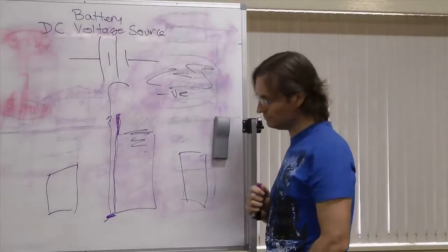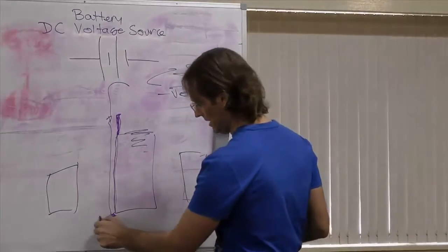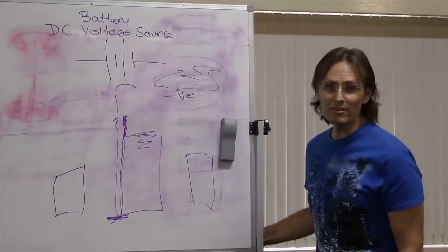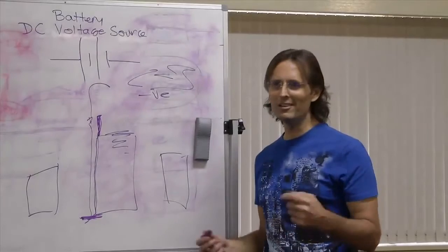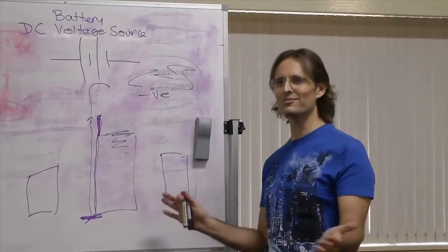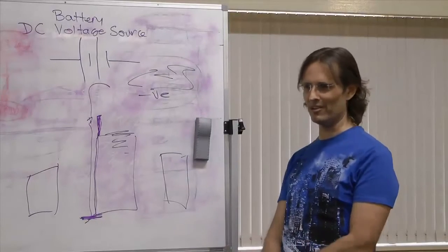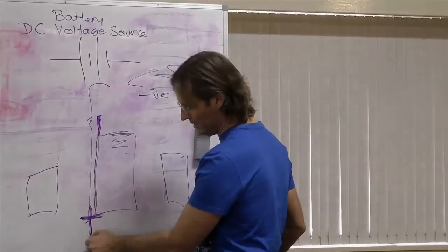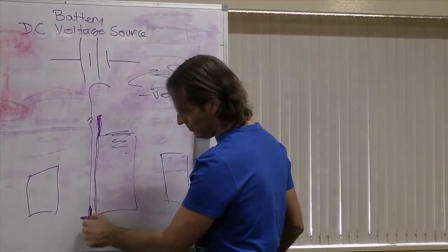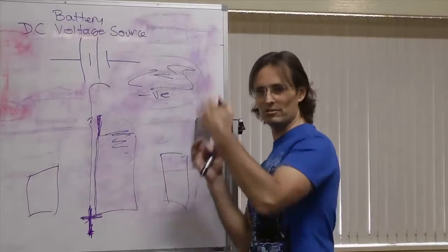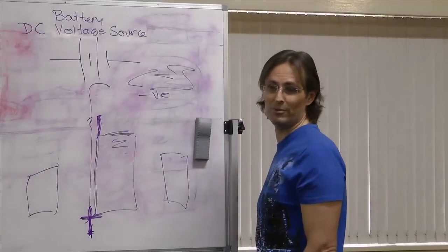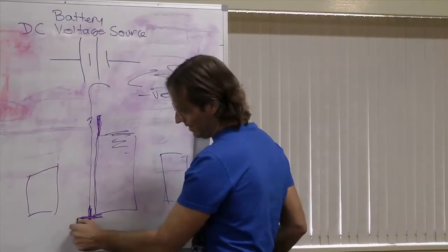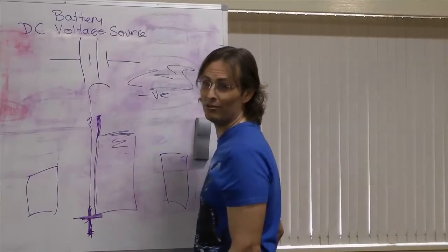With the bit that goes in the earth, so this is the same as what you said that all houses have too? It's the same, but much bigger. How deep does it go and what is it? Well, it depends on what type of earth and how much water is in the earth, whether it's clay or sand, there are a lot of variable factors as to the resistance of the ground. But a lot of times what they do is they suggest to bury it up to a metre deep generally if it's a house, with enough thickness to have large amounts of current flow through it without melting it. And that way it's got a lot of area that it can dissipate through. But it just depends on the type of soil as to how conductive it is.